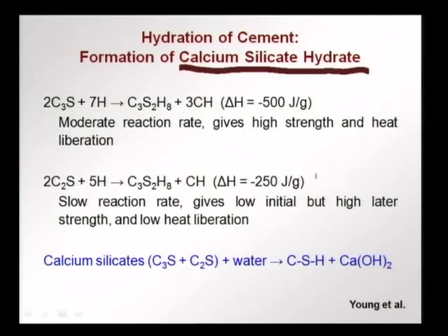The other compound which also reacts with water is C2S. Reacting with water gives us the calcium silicate hydrate and calcium hydroxide along with some heat. This is a slower reaction. Initially it does not impart a lot of strength, but later on it gives a high amount of strength. There is lower heat liberation in this reaction than in the former.